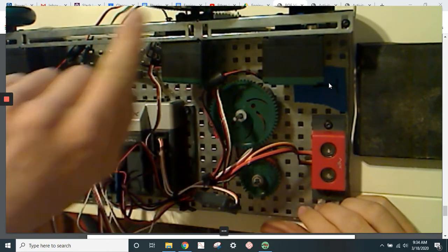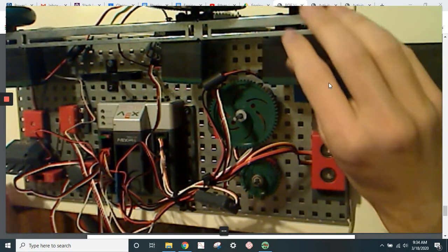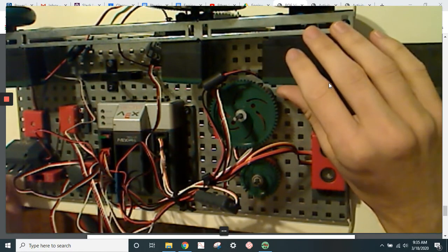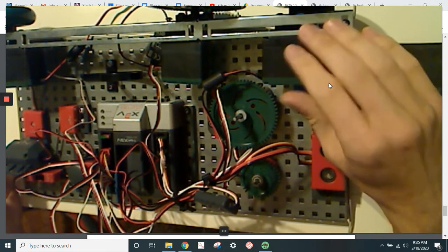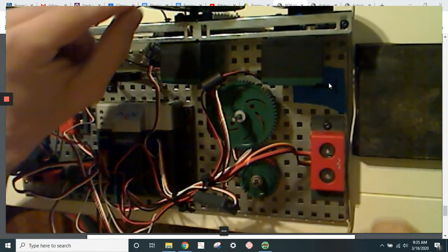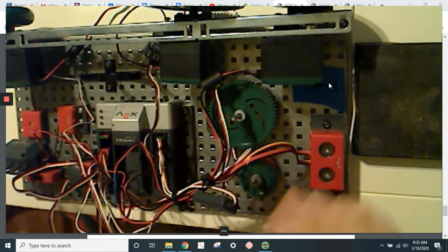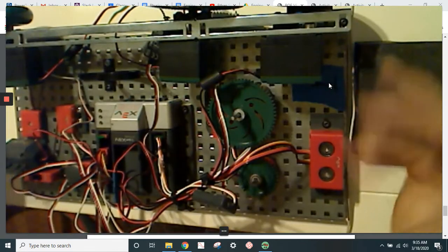But it's very useful because I can set it to a precise position, whereas the motors, I can't necessarily do that. I can run them for a set period of time and at a set speed. The speed is determined by the current I send through that motor, but I can't set them to a specific position. In the servo, you can do that. So servos become very useful if you want something at a specific position. So those are our outputs.